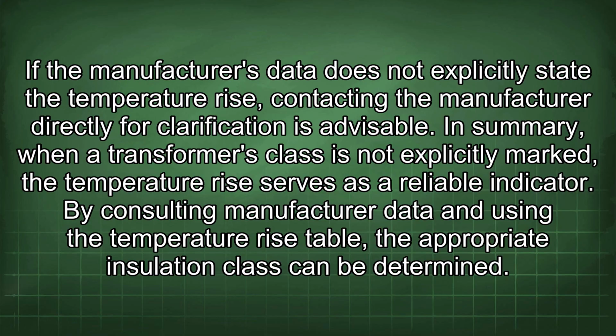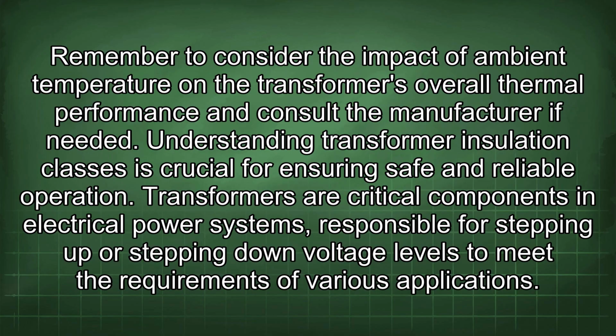In summary, when a transformer's class is not explicitly marked, the temperature rise serves as a reliable indicator. By consulting manufacturer data and using the temperature rise table, the appropriate insulation class can be determined. Remember to consider the impact of ambient temperature on the transformer's overall thermal performance and consult the manufacturer if needed. Understanding transformer insulation classes is crucial for ensuring safe and reliable operation.